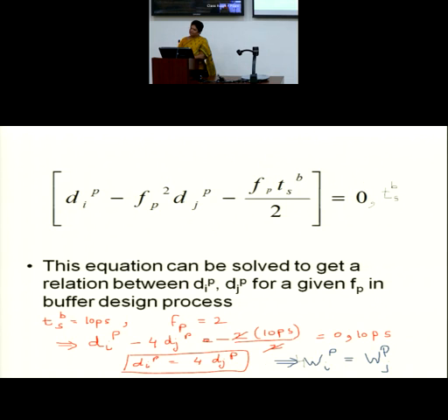What W you should have, so that ultimately the delays that you get because of that W keep the skew within bound. Okay, so this is equal to 0, and now suppose my budgeted skew is 10 picoseconds. That is what I have. I know the value. If my budgeted skew is 10 picoseconds and the factor by which slow and fastness is increasing or decreasing is 2, suppose it is 2, I substitute the expression over here.